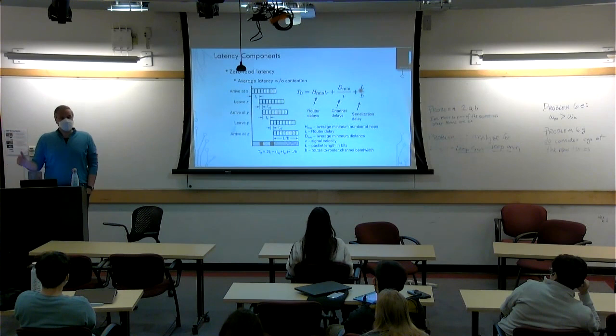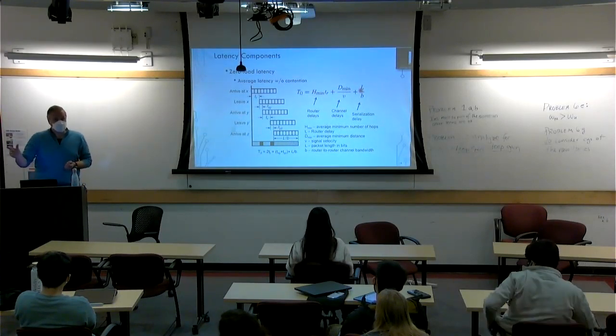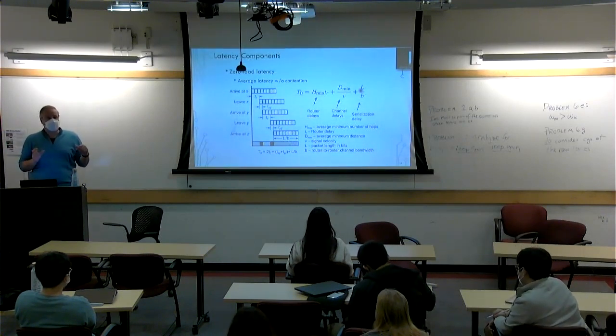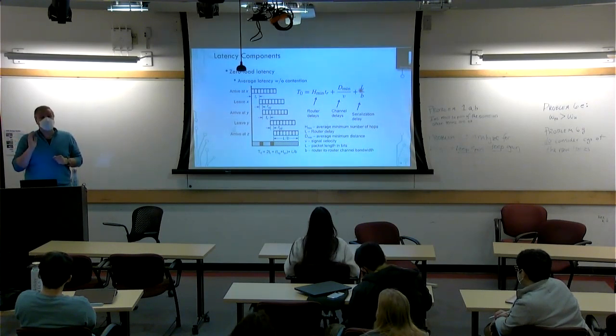Yes and no. As I said, in networks, it depends on what matters to you. Does fairness matter? Does the overall throughput matter to you? On which types of patterns? There are some patterns, especially for meshes, that are very nasty in that they create specific bottlenecks in certain parts if you have deterministic routing. We're going to touch on that very soon.